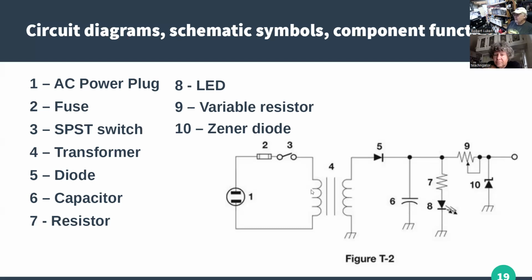So this little circuit is actually a power supply. So you have your 120 volts coming in here. This is more than likely, even though it's shown equal, a step-down transformer. So this might be 12 or 24 volts. It's being rectified by this diode because, remember, it only passes in one direction. So you're going to get a half of the AC waveform. It's going to get partially stored in this capacitor to kind of smooth it out.